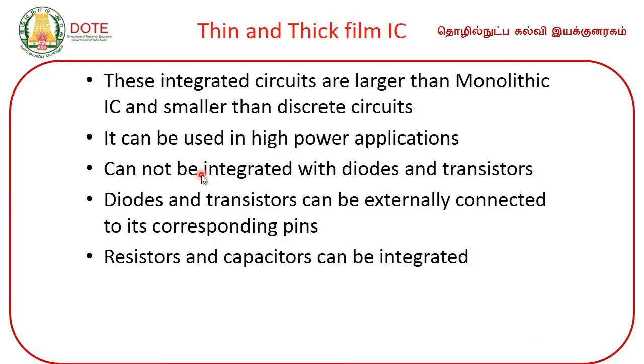But one important disadvantage with this technology is you can fabricate only the passive components, resistors and capacitors, but diodes and transistors you cannot. It cannot be integrated with diodes and transistors. Diodes and transistors can be externally connected to their corresponding pins.